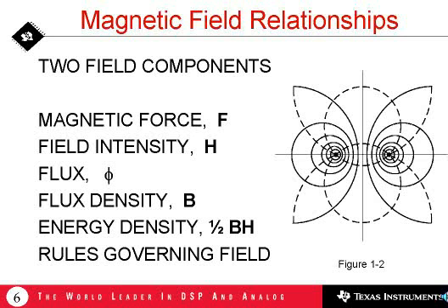It turns out that most of the energy stored in the magnetic field is in the region between the two conductors, the region of high energy density. Although the magnetic field extends to infinity, the energy density drops off much more rapidly, moving away from the conductor pair, than the volume increases.